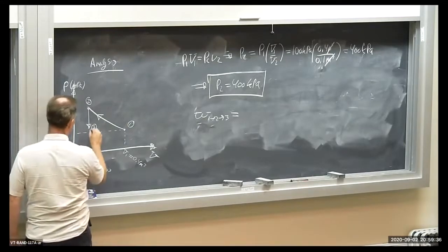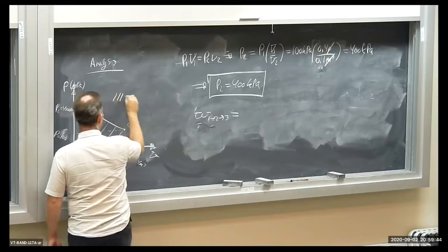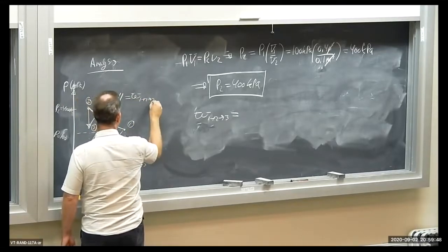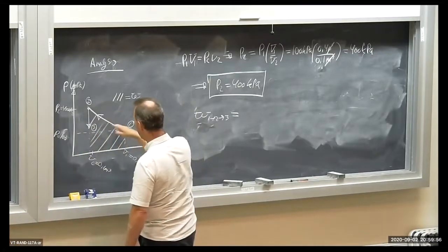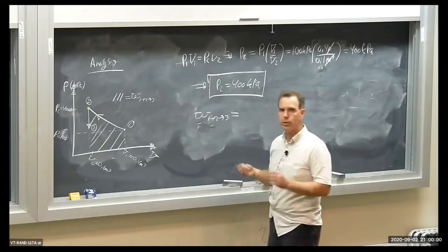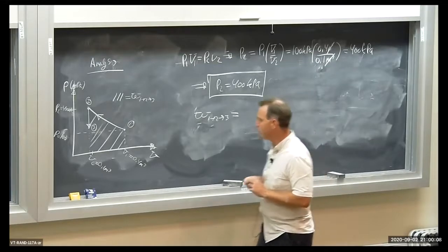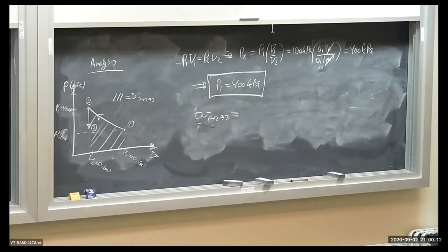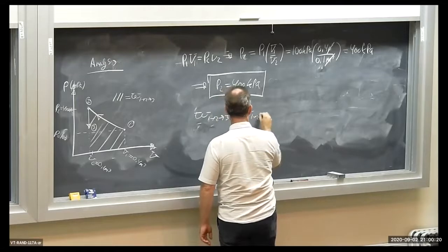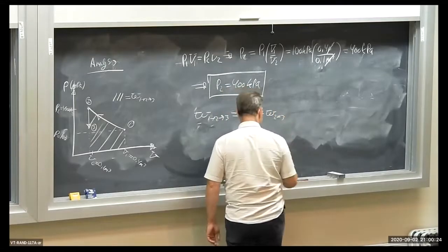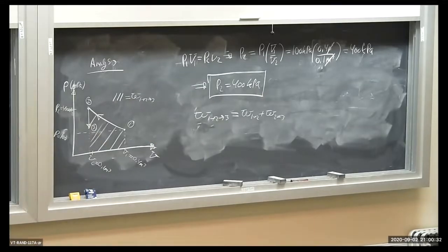Of course, the work is the entire area under the curve. So the boundary work from 1 to 2 to 3 is given by the area under the curve. This is not a straight line here, so you cannot estimate the area under the curve using some sort of geometry. We have to calculate the boundary work over the process. So what is the work from state 1 to state 2 and then to state 3? Well, that's equal to the sum of two works: the work from 1 to 2 plus the work from 2 to 3. It's a two-part process, so we have to calculate both works.